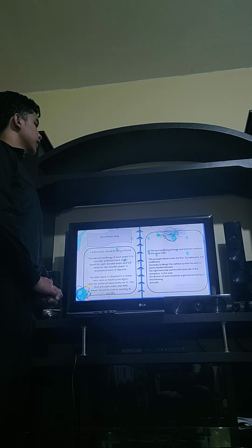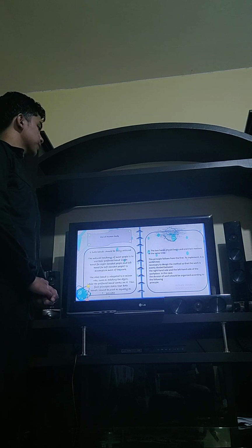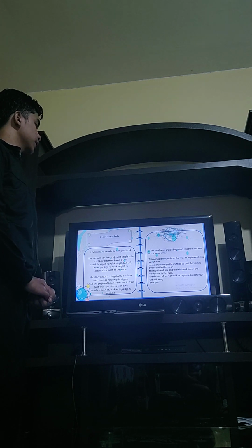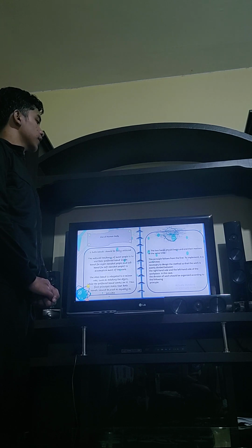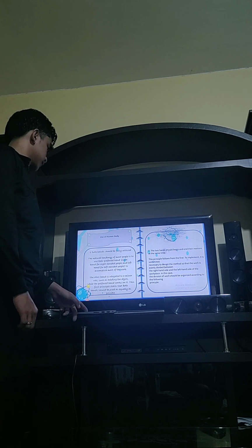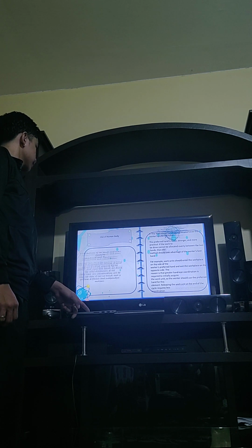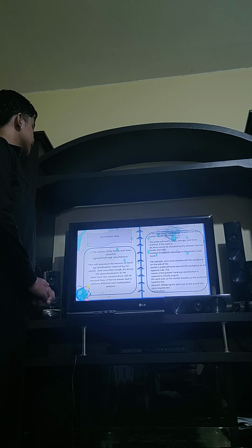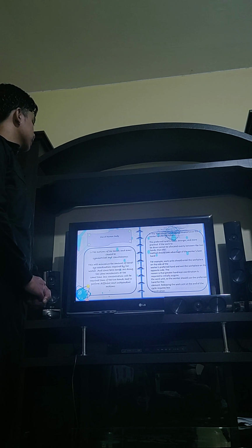Number 2, the two hands should begin and end their motions at the same time. This principle follows from the first. To implement it, it is sometimes necessary to design the method so that the work is evenly divided between the right-hand side and the left-hand side of the workplace. In this case, the division of work should be organized according to the following principle. Number 3, the motions of hand and arm should be symmetrical and simultaneous.